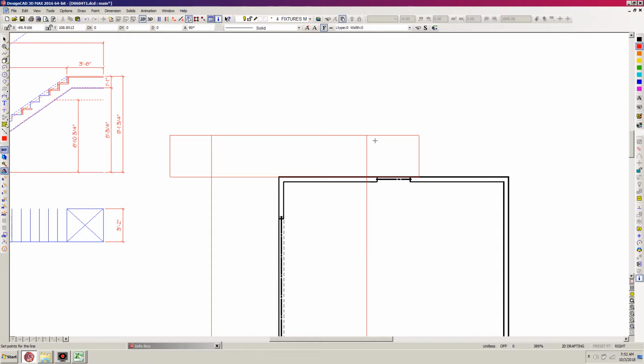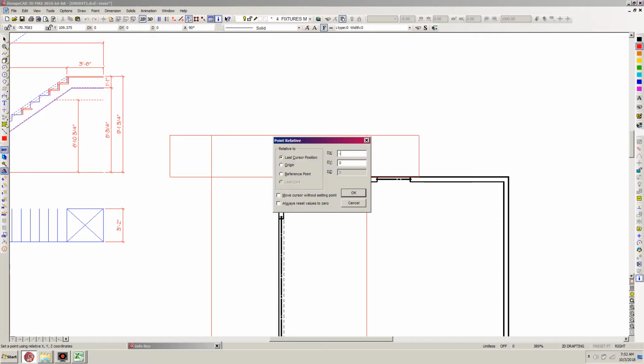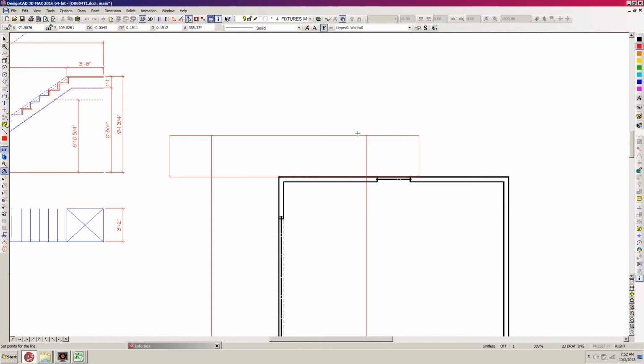So I'm just going to hit V for vector, and we know they're 10.5 inch treads, so I'm going to gravity move and -10.5 inches, and hit H for orthogonal mode, and come on down and just hit K. So now this 10.5 inches, just for this upper tread here, I'm just going to click on that and set a handle. Go over to set selection handle and right click here, and then hit my scroll button to activate the command. And I'm going to hit H. I don't need to be in orthogonal mode anymore, so that toggles out.